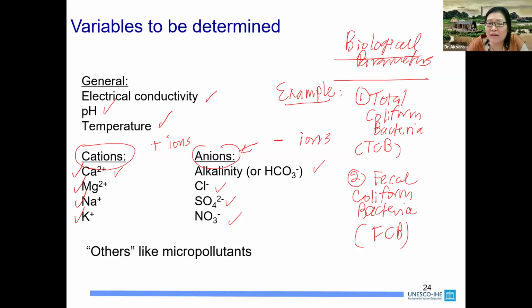And the second thing is that groundwater taken from the unconfined aquifer system is always contaminated with bacteria, because the unconfined aquifer is connected directly to the surface water. If you have human activities on the surface, like a school or domestic communities, you will always find bacteria from the sewage system leaking into your groundwater.